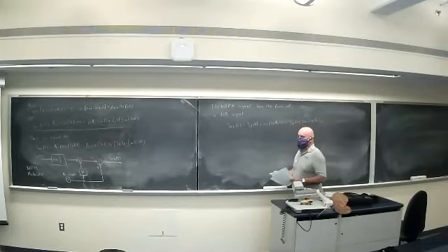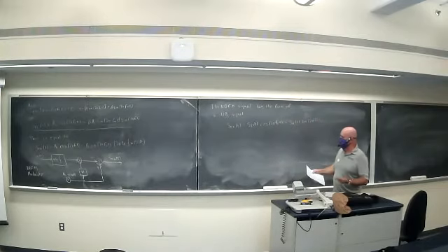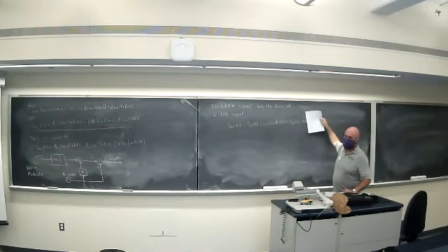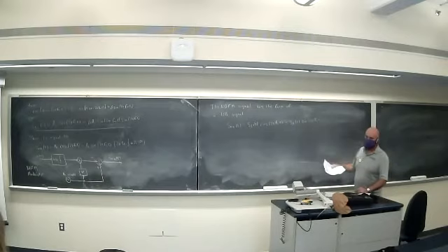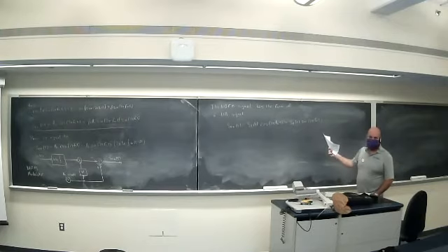Okay, and this was true for standard AM radio, where you didn't even have the quadrature signal. You just had the in-phase term that was 1 plus the message, the message with a DC offset. And it was true for double sideband, again, where you didn't have this. But it was also true for what we called the quadrature AMs, which had both of them. And it's actually a general representation for any sort of narrowband signal.